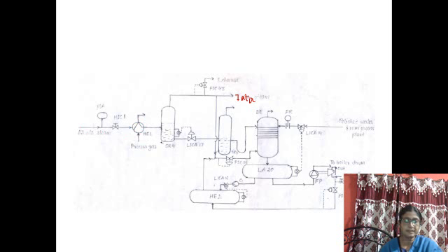This 7 atm steam line is used here through another pressure control loop, PIC 36, to the lower portion of the drum. So why does another pressure control loop exist? Because it is essential that the steam entering the lower portion of the deaerator unit must be of 7 atm.